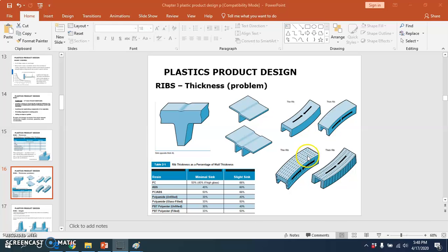This is the example of glass-filled material with high shrinkage in the cross-flow versus flow direction. The effect of rib thickness on warpage can be quite different. This one has glass fiber. For a thin rib it curves outward, for a thick rib it curves inward, the opposite.